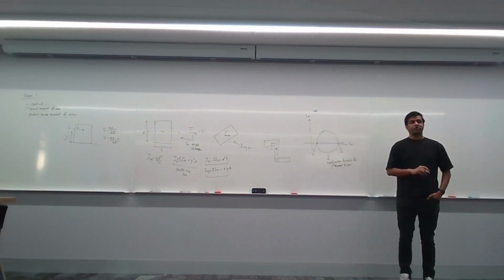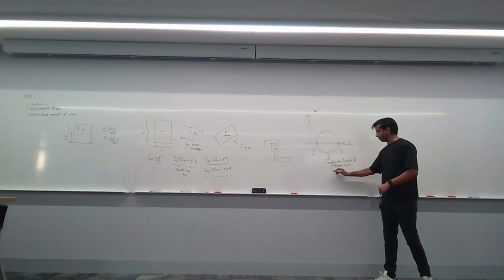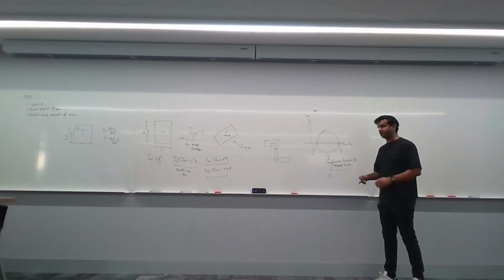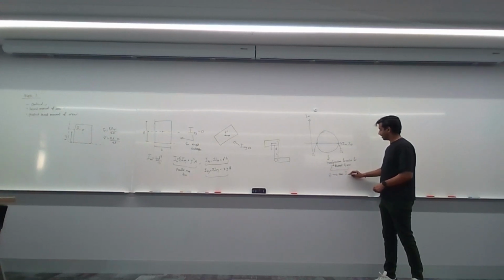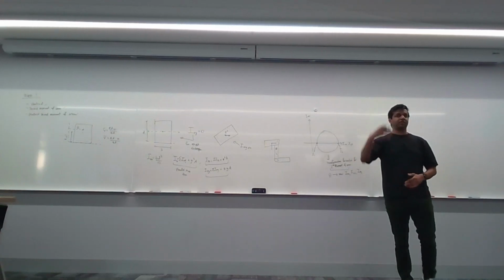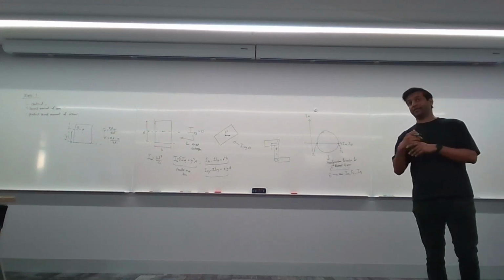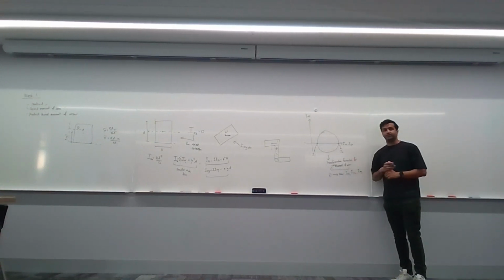What that means is for a given angle of rotation, that's called the angle of rotation theta, you can find the new Ixx or Iyy or Ixy. I'm not going to write the formulas up here. There's 3 or so different formulas. They're in your lecture notes. Go have a look at them and keep them on hand in case you need them, right? These are your transformation formulas for second moment of area.